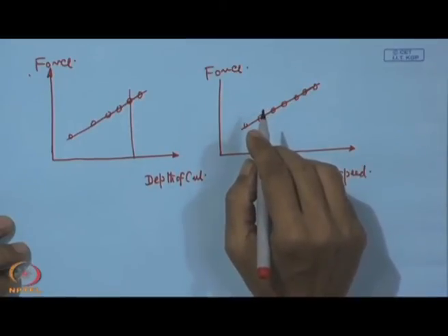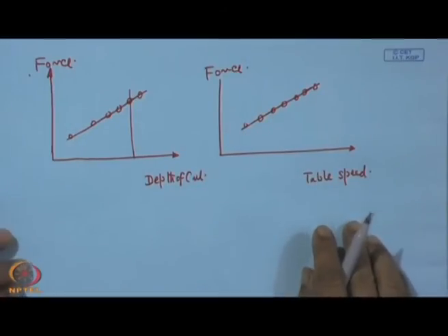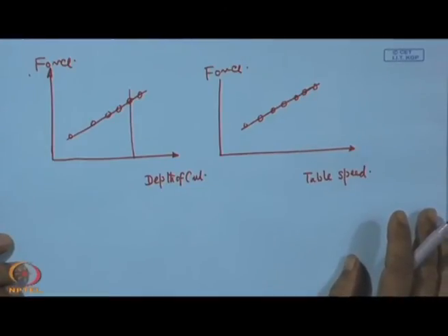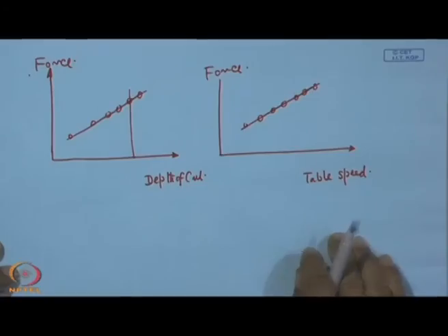But if it is not the case, then definitely we have to take some measure so that we can improve the situation. It can be either having a proper bond coat or having proper substrate preparation, particularly the mechanical working of the substrate, mechanical preparation of the substrate, and also having proper cohesion in the coating.